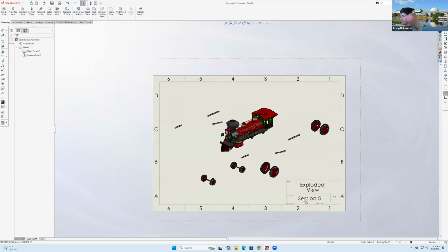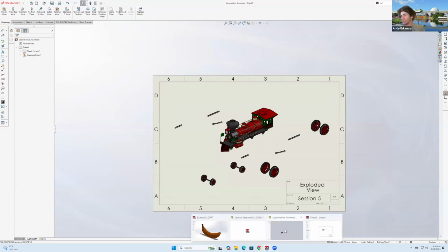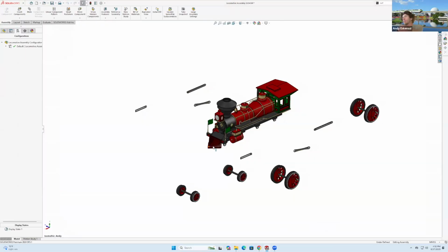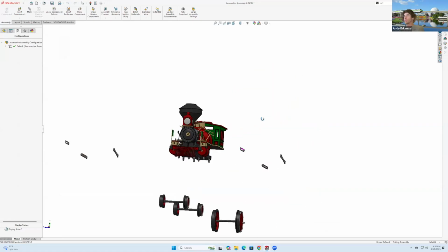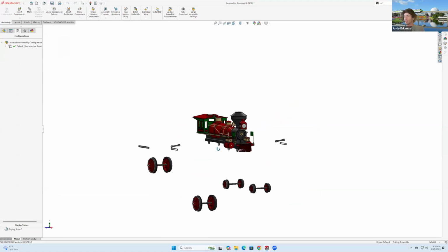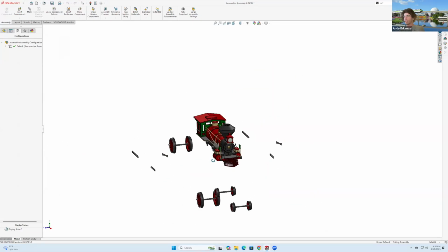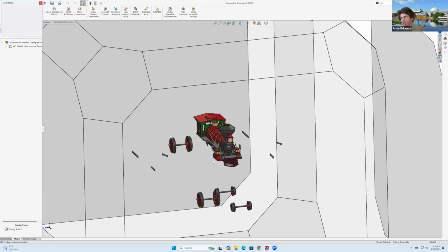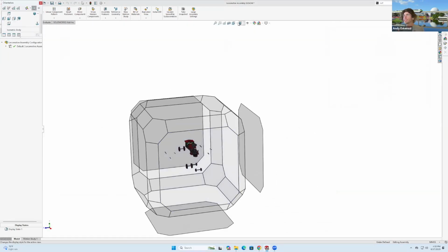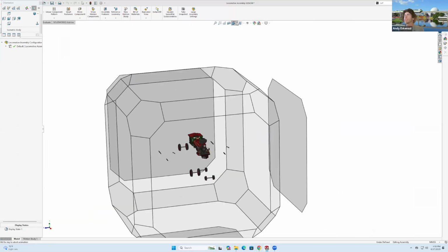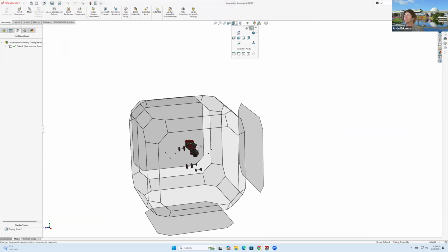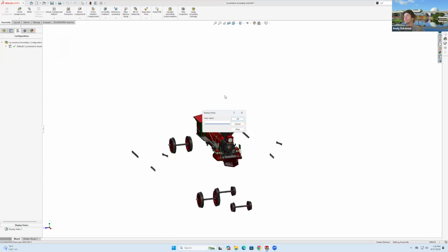Okay, so one last thing that I just figured out last second is that if you go to SolidWorks in here and say you're happy with this view, or you want this view to be on the assembly, something like that. I'm just rotating it in there. Then you click on the spacebar, and then these guys appear up here, where it says view orientation. And then in view orientation, there's this little telescope of sorts. You click in there, which says new named view, and you can call it, I don't know, isometric 2.